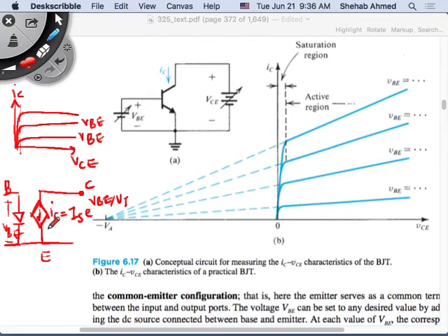What does this equivalent circuit model mean? It means that if I change VBE here, the voltage across my input, due to current, basically, so I've pushed enough current, I've forward biased this diode, I've created 0.7 volts across this diode. So changes in VBE will cause a current in the output that is independent of VCE. That's what our equivalent circuit model told us, right?